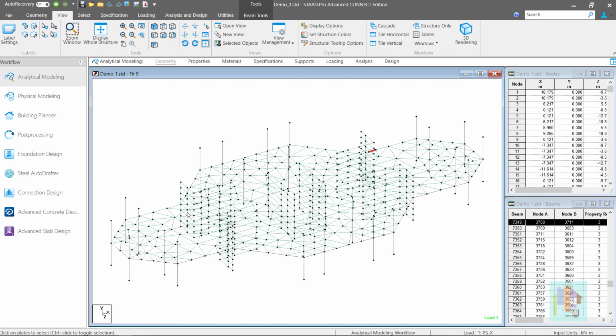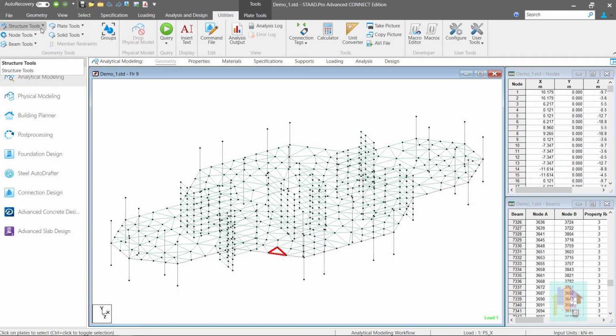For a large irregular panel with haphazard beam layout, manual adjustment is very tough. Also, no warning is reported in the output file for this, though this is a major modeling issue. Only way to identify these problems is by using the connectivity check tools from GUI.